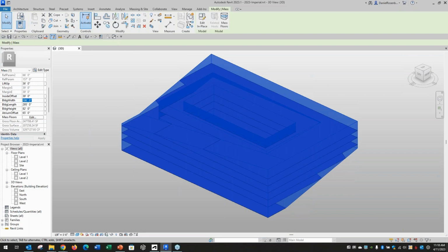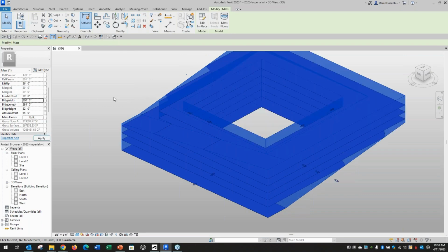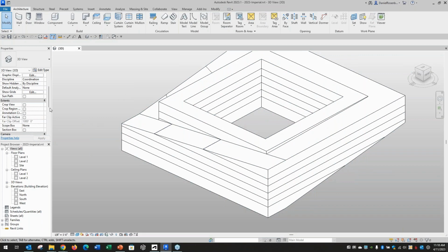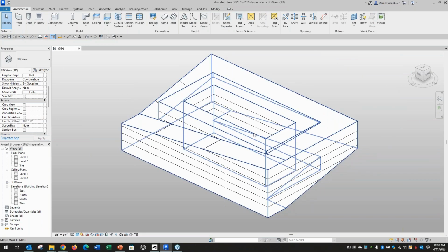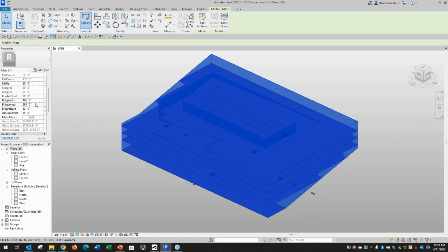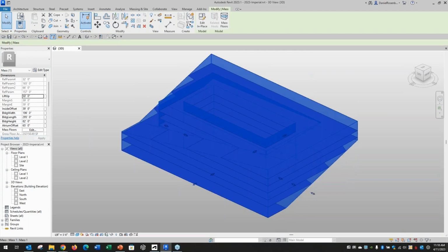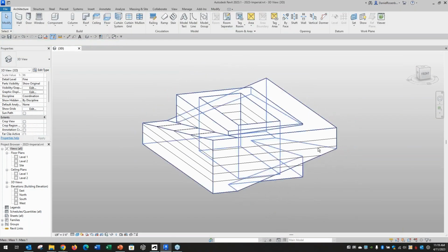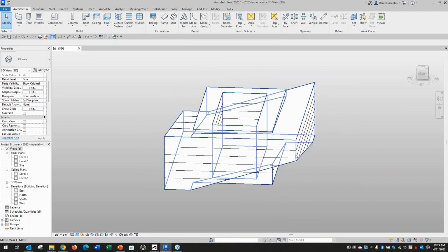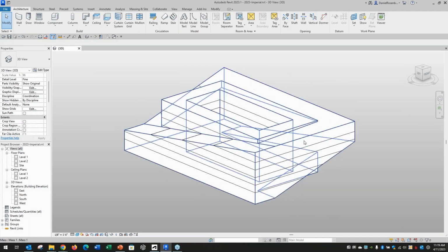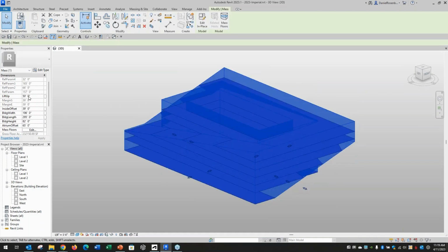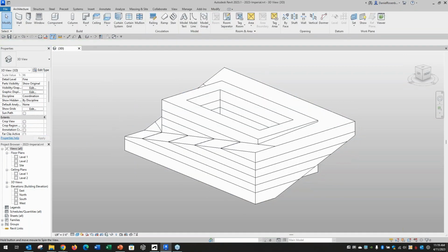Maybe I want the building width to be closer to 300, and I can extend it out that way, or let me undo that. This one's kind of exciting. I've got this lift up value here. Let's bump that up a little and see what happens. So that changes this little outer height of this thing right here. Bumps it up a little higher. Let's make it a little more dramatic here. Click on that, find this parameter value. Let's bump it up to like 60, just so you can see what's going on here.